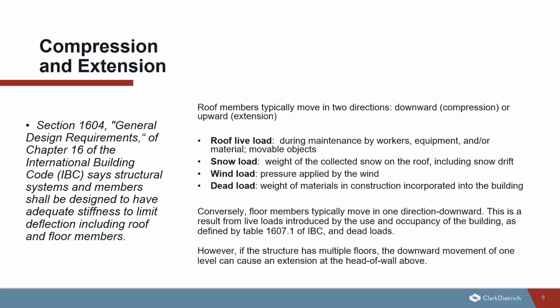So for the floor members, those typically only move in one direction, which would be downward. That's going to be a result of the live loads that are introduced by the use and occupancy of the building, as well as the dead loads. If the structure has multiple floors, the downward movement of one of the levels can actually cause an extension at the head of wall above. So that's why it's also important to calculate those into your design.